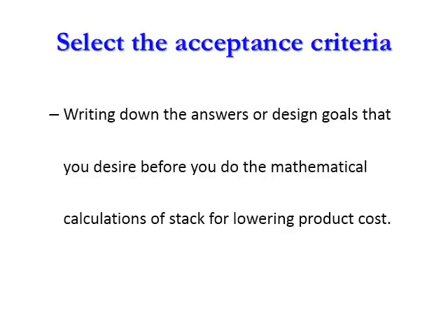Acceptance criteria. Select the acceptance criteria. Write down the answers or design goals that you desire before you do the mathematical calculations of the stack, for lowering product cost. That is the critical step in this stackup analysis: writing down before you are doing the stackup analysis.